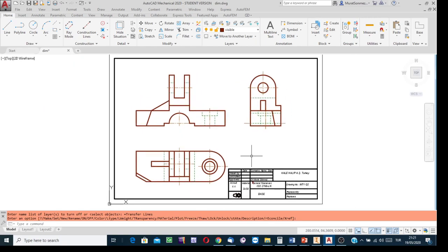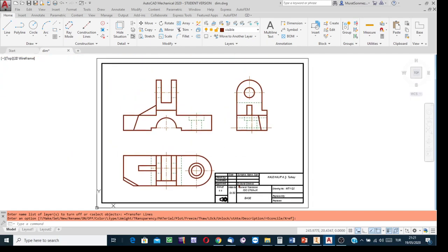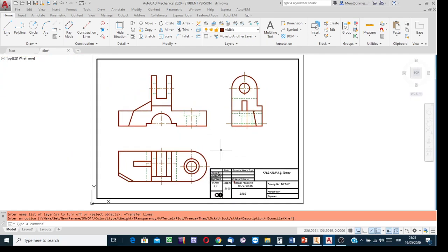Okay, drawing scale is 1 to 1. These are the views: front view, top view, left side view, because you know quadrant symbol is the first quadrant symbol, and I'm sure these are the primary principal views: front view, top view, left side view. I have the necessary symmetry axis, etc. The views are correctly drafted ones and ready to show the dimensions.